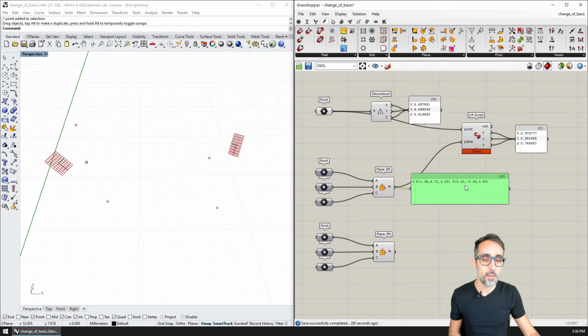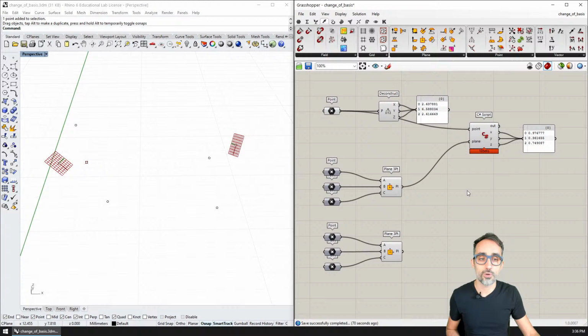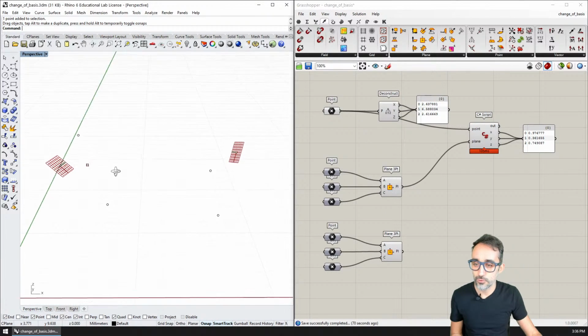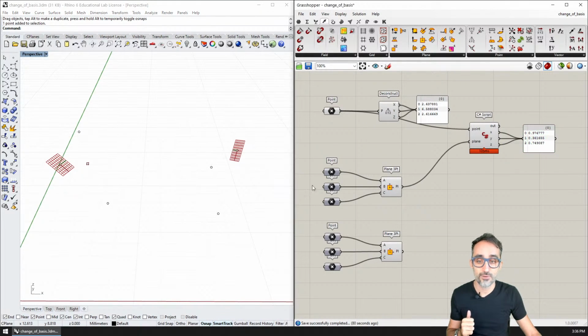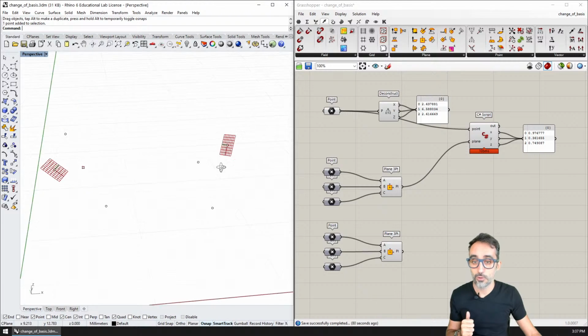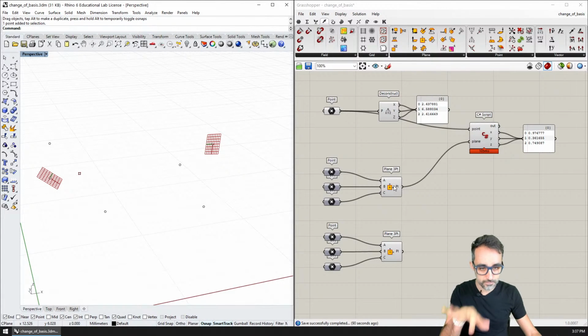And I'm going to be building upon the work that I have done in my previous gem, where we discussed how to, given a point and given a reference system, find the local XYZ coordinates of that point for that coordinate system or for that plane. What I have done is I have created a second plane, also from 3 points, using functionality that is available in Grasshopper.